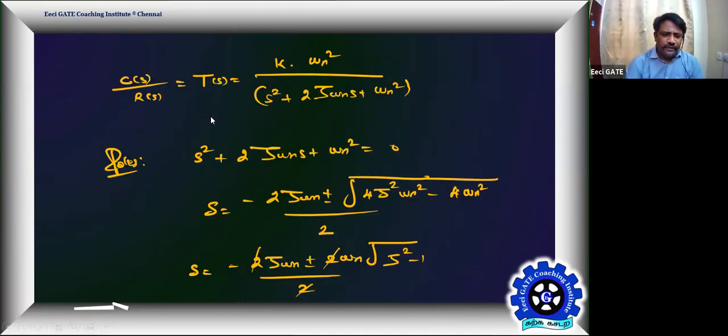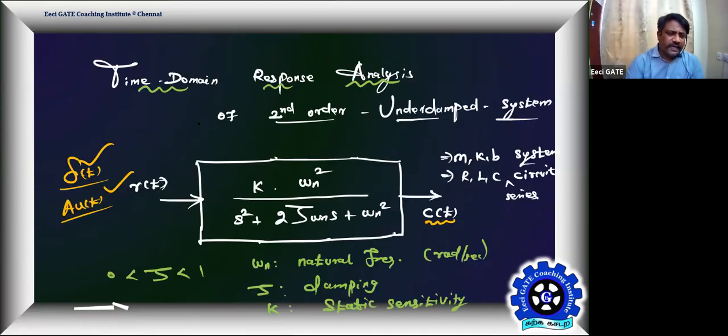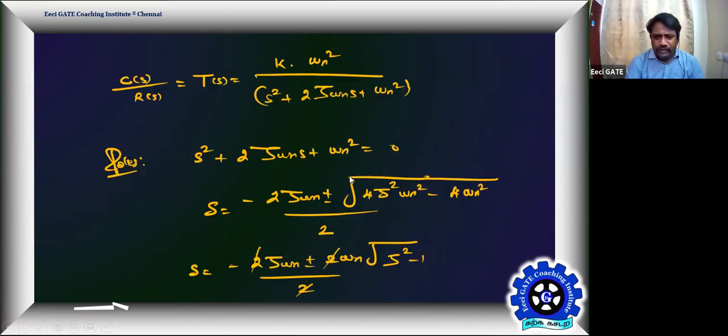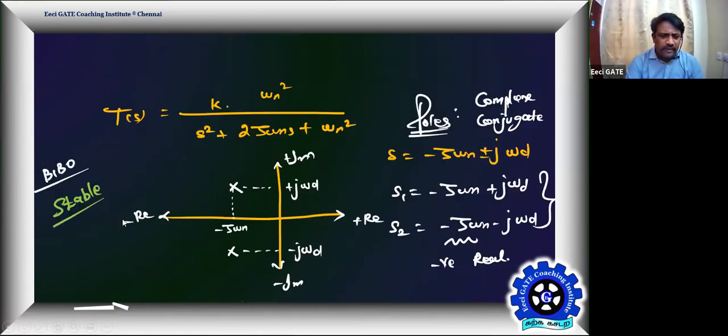Now we are going for the responses. We are going to apply an impulse input as well as a step input. Then the response is going to converge. It is going to produce stable responses only. So c of t will be converging responses only, because now we know where the poles are. Therefore, we can conclude the BIBO stability of the given system. We'll see how they are converging. That means the output response is bounded even during transient. That's what BIBO stability also says.